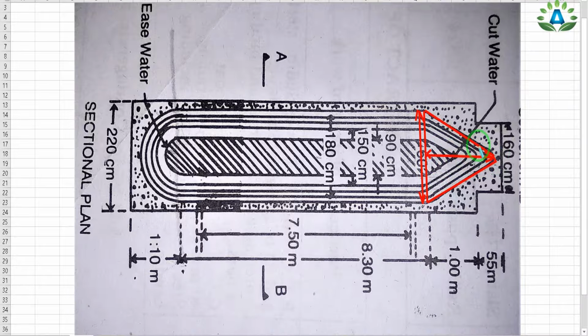And one thing you need to know is this cut angle is at 60 degree. That means this total angle will be equal to 60 degree, and we can use the Pythagoras theorem to calculate this total height. Since this is 60 degree, this small angle will obviously be 30 degree, that is 60 by 2. And we know that this portion is 180 centimeter that we have already calculated from our section on AB. Since this is our midpoint, this small portion is 180 by 2, that is 90 centimeter from this side and 90 centimeter from this side.